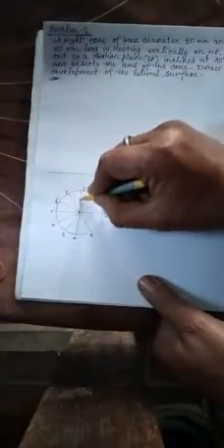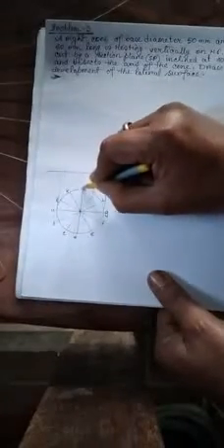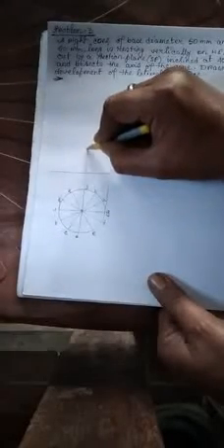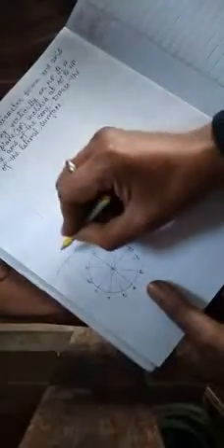Now this is the axis. If we draw a projection line, this is the central axis of the cone, and we draw the apex here. This is the base of the cone, and from here to here is 60 millimeter, as given. You can see the axis length is 60 millimeter. So this is the apex, the top point. Now join these two.